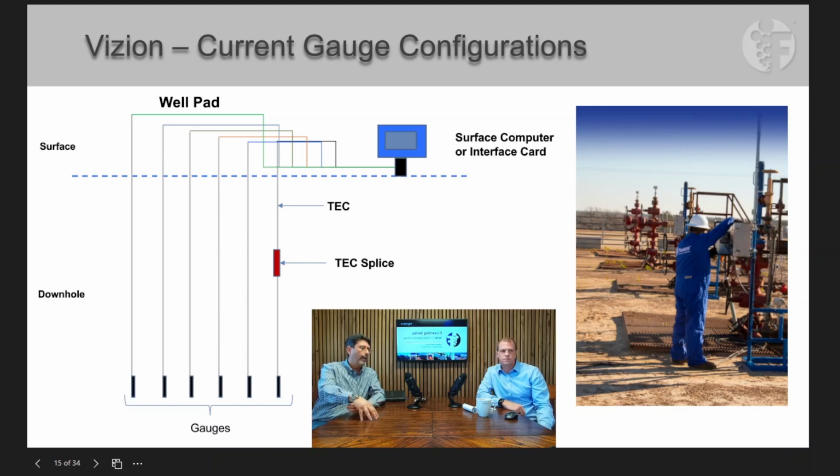If you have a well pad with 4 or 6 Flowco downhole gauge systems, we can always configure one computer for all those wells. So they can actually power up all those wells and also pull the data from all those wells, and store the data and transmit the data of all those wells with a single computer to their SCADA system. Oh, that's nice. So you can reduce your footprint and tie multiple gauges into one system. Correct. Okay. Yeah, that's good to know.